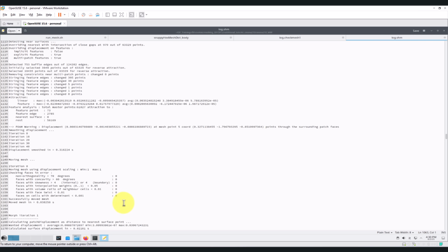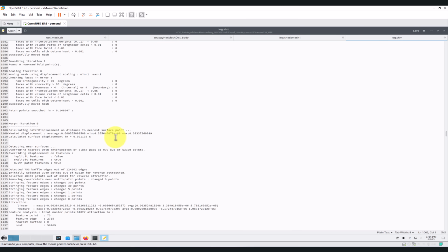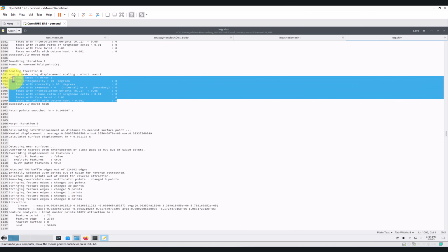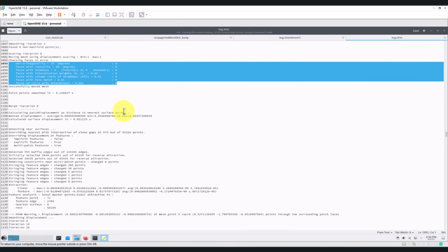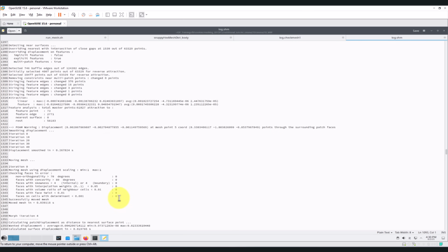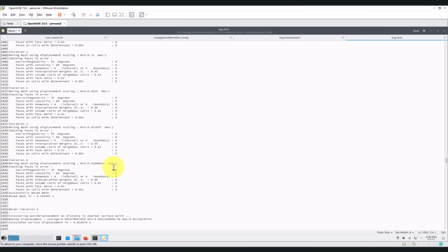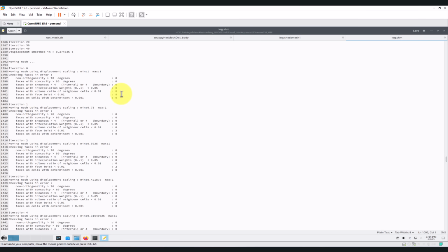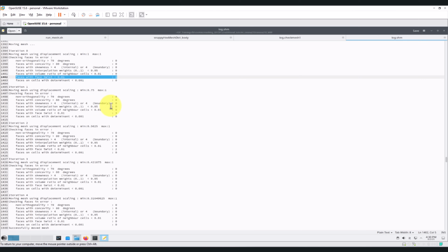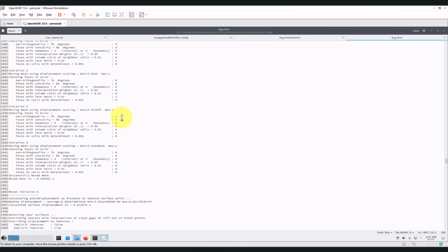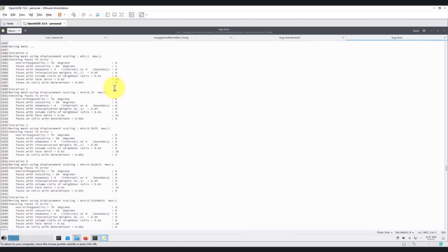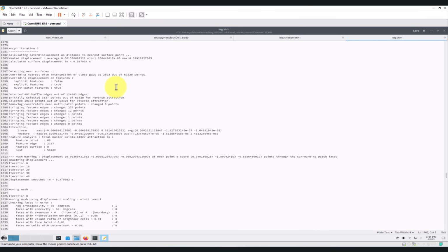Uniform cells. So probably you're going to see some issues if you have no stretching in the background mesh, or you did something really wrong. But other than that, this should always be 0, 0, 0 now. So no cells violating your criteria. If you see some cells there, be careful. It can be an indication that maybe you can improve something here. You have this one face with face twist. I think I would prepare a video just to show better what this is. But usually this is close to the surface where you have the body, but pretty much everything is great. Okay, and now you pass.